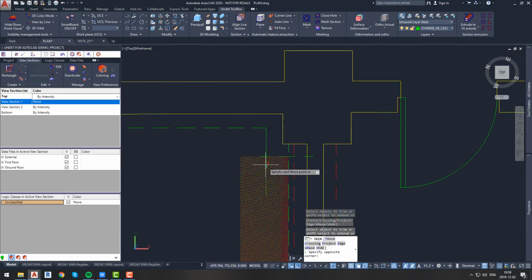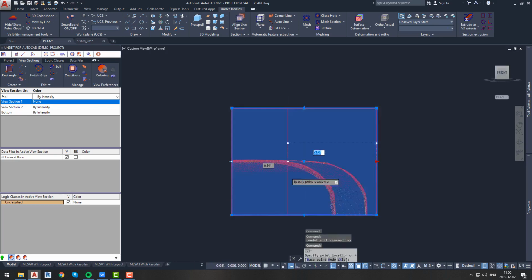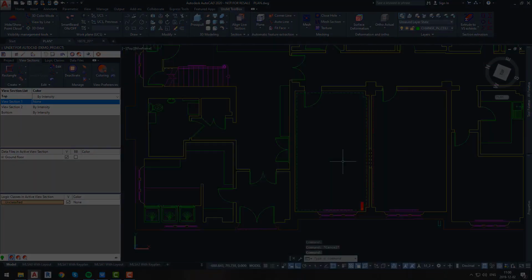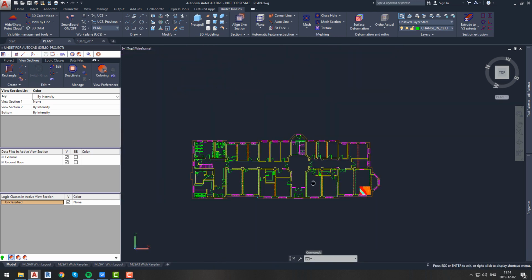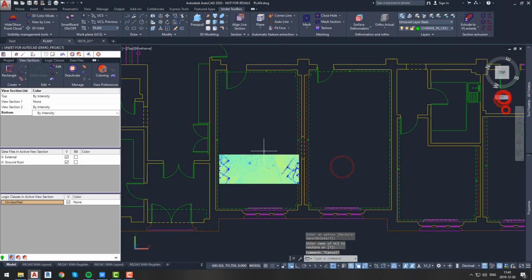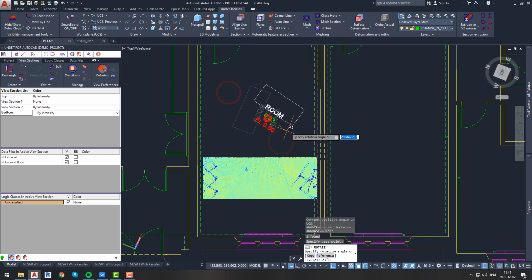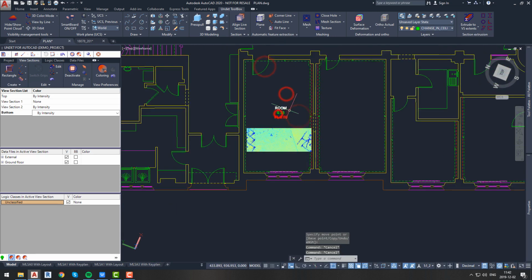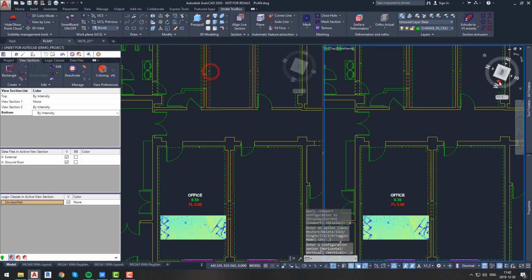It is really easy to indicate every object in our drawing since we are using a template with all layers that we need, and every line has its own settings, so with time you can read drawings really fast. After drawing ceiling objects in all other rooms, we can take a look at our plan before starting our last step, which is annotating. So first we will start from adding an annotation block to each room. This block will allow you to add room name, and add floor level and ceiling height annotations.